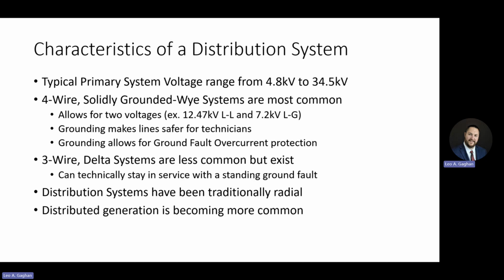So what ends up happening on those systems is, if a ground fault does occur, that particular phase, let's say it's phase A, will go to 0 volts. And interestingly enough, the line-to-line voltages will actually all stay the same. I don't know if I can draw on here. So what will end up happening is we'll call that ground. If you think, okay, phase A had a ground fault, the voltage is going to go to 0 like ground, but all of your line-to-line characteristics